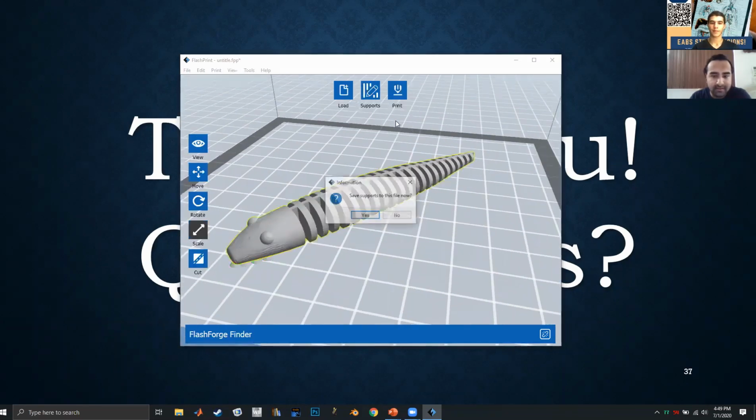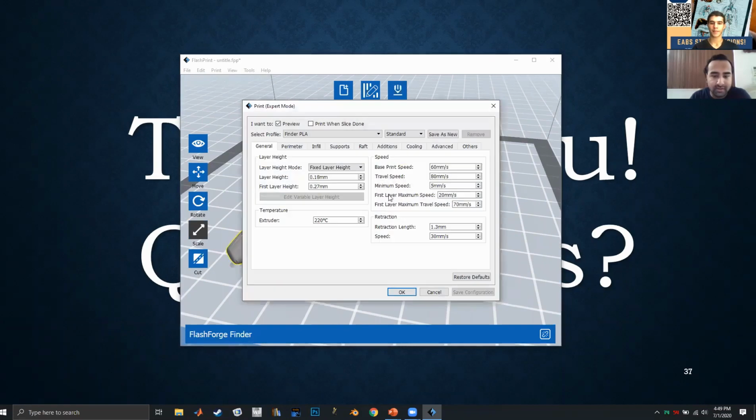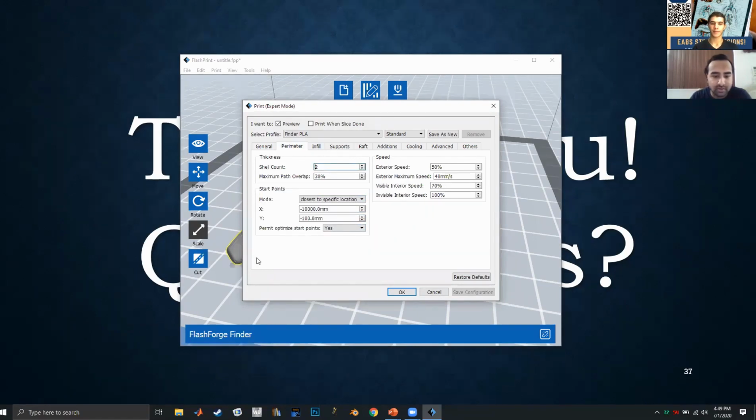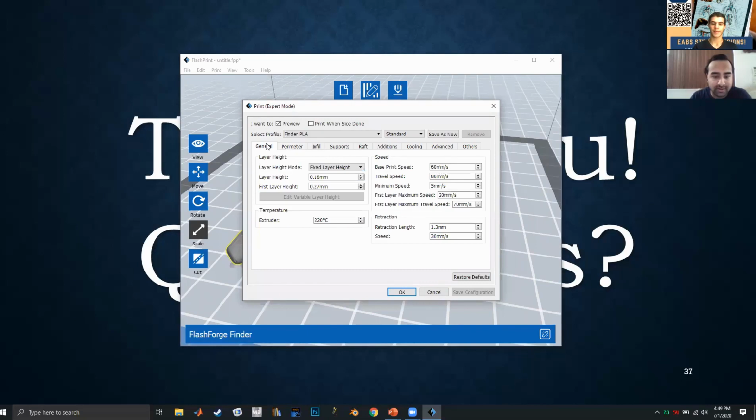And then you can go ahead and do your 3D printing. As I mentioned, you have the option of controlling your infill density, the pattern that you use, the perimeter count, so how many outside structures you require. You can go very deep into it, and how complicated you want all your settings to be goes way beyond the purpose of this workshop.